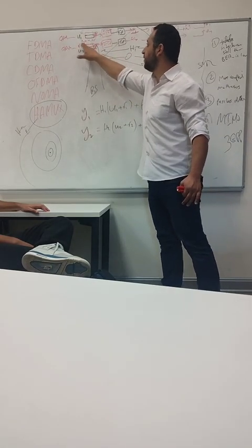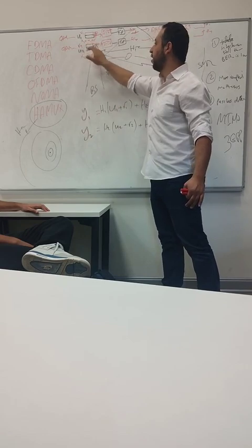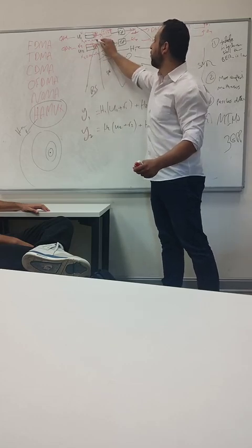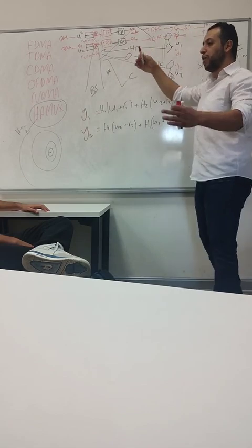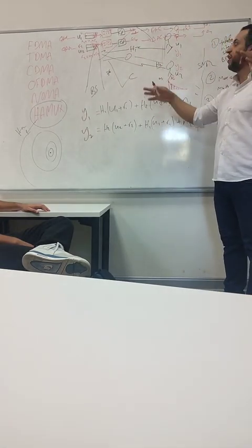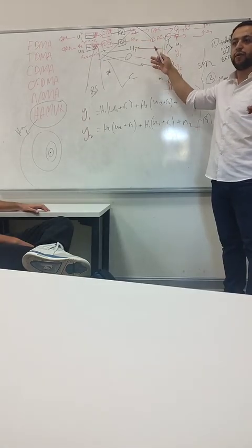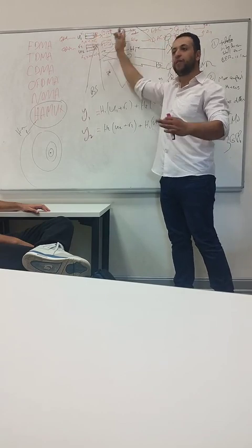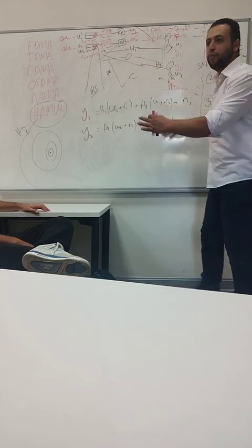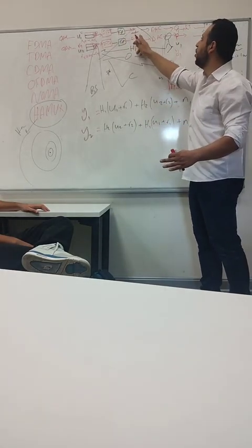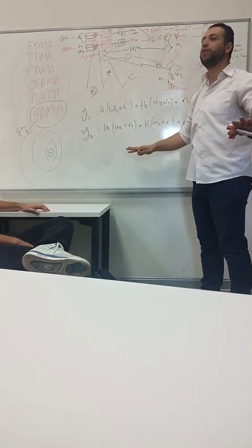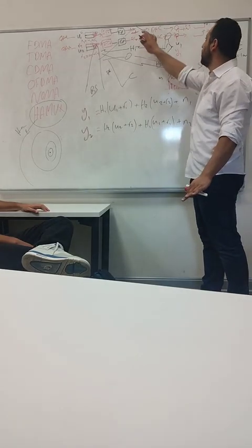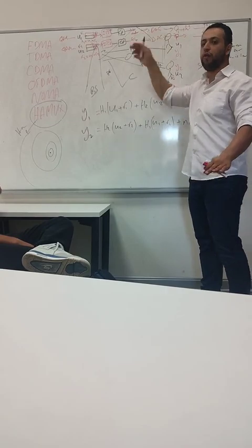And then the signal becomes, in the frequency domain, x1 equals u1 plus r1, and x2 equals u2 plus r2. And then it passes through the normal OFDM operation, where you have the IFFT, inverse fast Fourier transform. It takes the signal from frequency to time, and then you add the CP to protect your signal from multipath, and then you add windowing and filtering to suppress the side lobes a little bit and get rid of the adjacent interference and out-of-band emission.